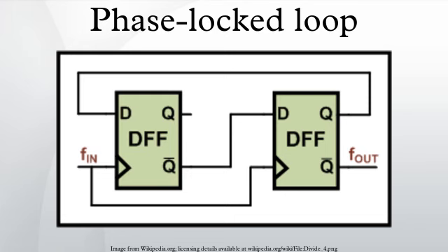Clock generation: many electronic systems include processors of various sorts that operate at hundreds of megahertz. Typically, the clocks supplied to these processors come from clock generator PLLs, which multiply a lower frequency reference clock up to the operating frequency of the processor. The multiplication factor can be quite large in cases where the operating frequency is multiple gigahertz and the reference crystal is just tens or hundreds of megahertz.